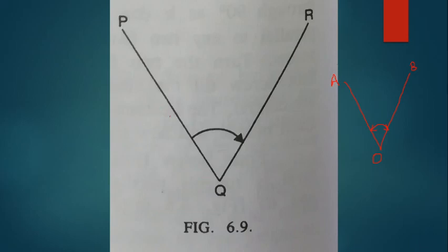And we know when you operate the lower clamp and lower tangent screw, the reading will not change. Now for the second time, the telescope is exactly in line with the QP line. Now I need to measure the horizontal angle for the second time, again with face left only.